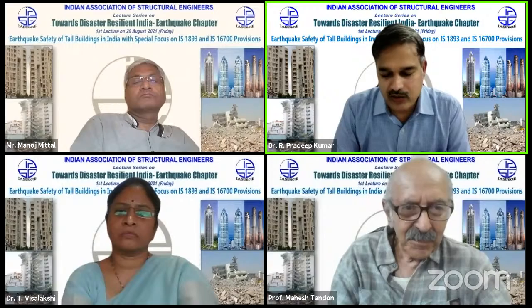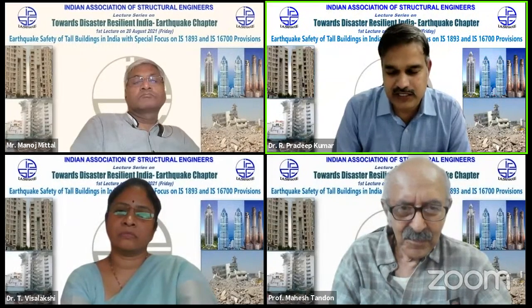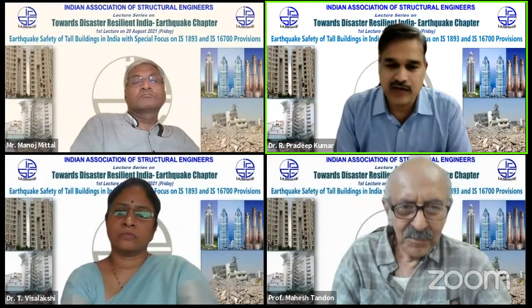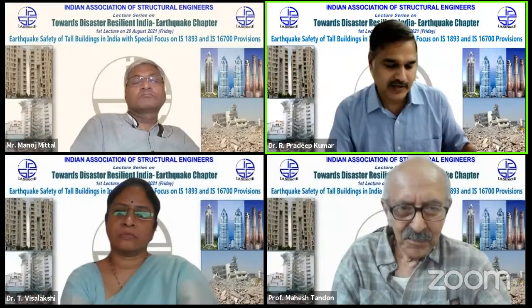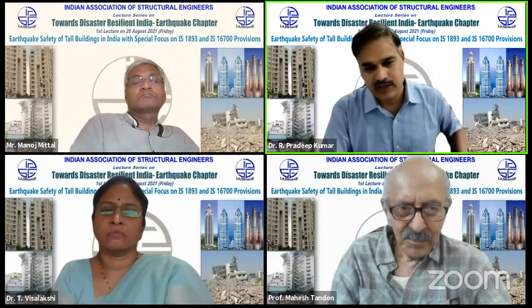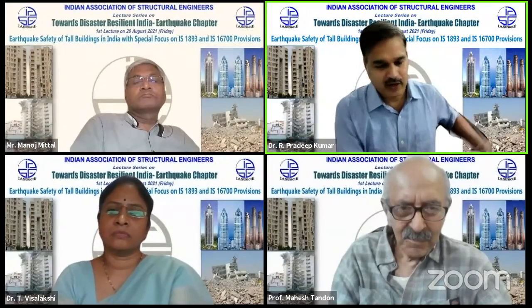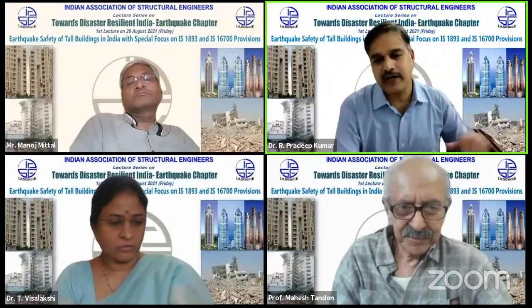Unfactored loads are for lateral drift deformations, and factored loads are for getting stress resultants for design. So these are the two things: for capacity, factored loads; for deformation, unfactored loads. For deformation, the cracked section values are different for both the cases.